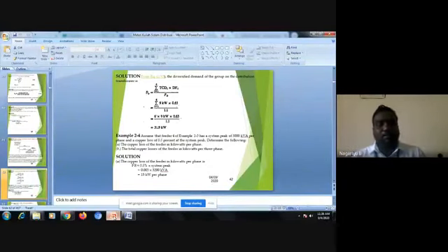With respect to that 0.5%, I will have 0.5 divided by 100 into system peak, which is the I square R. The total copper loss is equal to I square R, which is 0.5% of system peak. 0.5% is nothing but 0.5 divided by 100, so 0.005 into system peak, which is given as 3000.